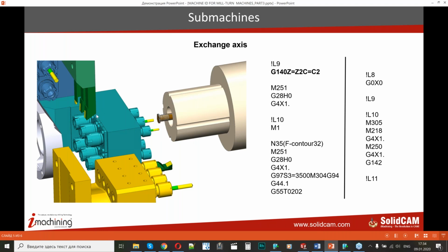Some other machines can combine these operations if they can divide these axes inside. But this machine needs axis exchange commands to operate. And after I finish, I will add the special code to cancel this mode. It's G142. You can refer to the Mitsubishi manual, and I believe there are more explanations if it's not really clear.